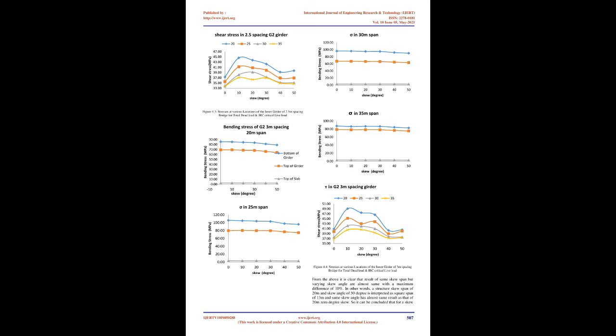The third loading case is the dead load of the bridge, in which the total weights of the reinforced concrete deck slab, the longitudinal steel girders, and the transverse diaphragms are applied on the bridge as a uniformly distributed load. The fourth loading case is the superimposed dead load, in which loads due to crash barrier, railing, wearing coat, and footpath are applied according to their location on the deck slab.